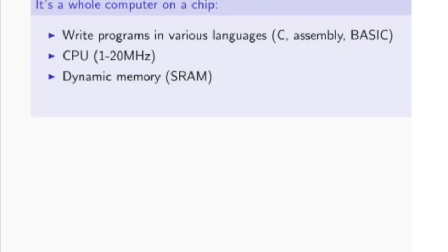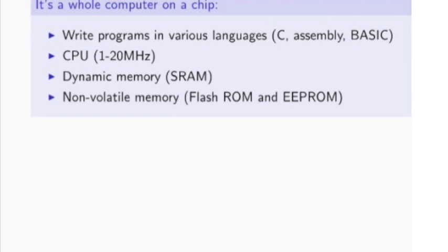This is normal old RAM. And then you've got some non-volatile memory. It stores programs in flash, ROM, and then there's a tiny little bit of EEPROM, which you can think of as storage that will be around when the power goes out, kind of like with a hard drive. And then you've got all the other peripherals. It's a whole computer system on a tiny little chip.